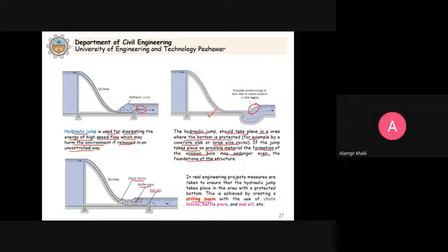Even if there is any problem with the turbulence of the hydraulic jump itself, protection is still provided, and after this the water can flow with greater depth and less velocity, and it will not pose a greater threat to the channel section. Clear?